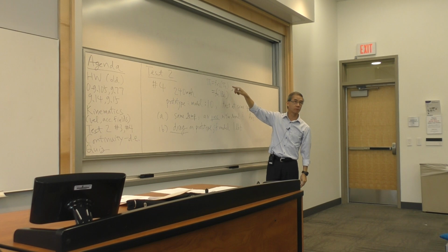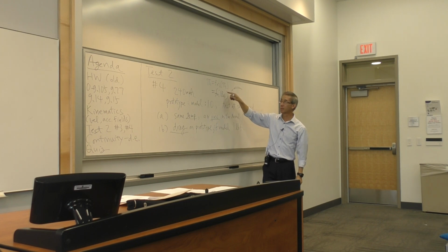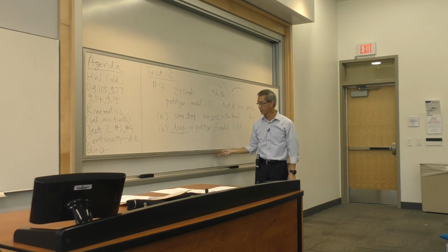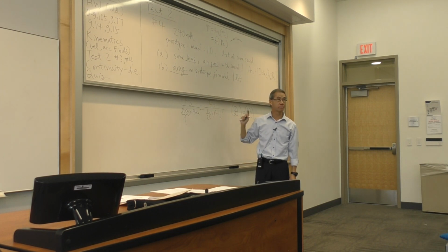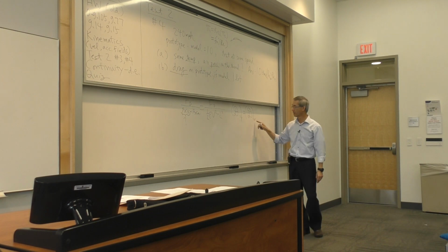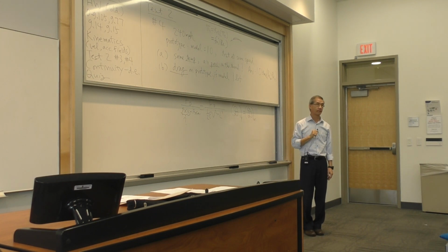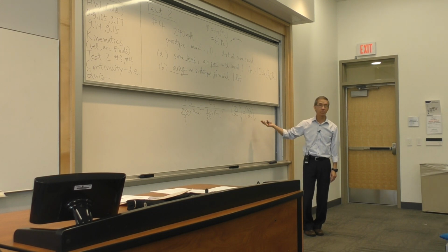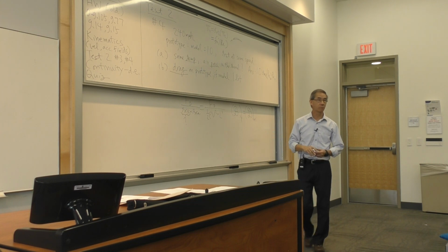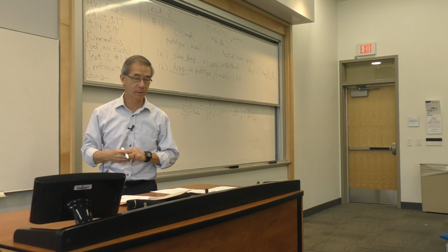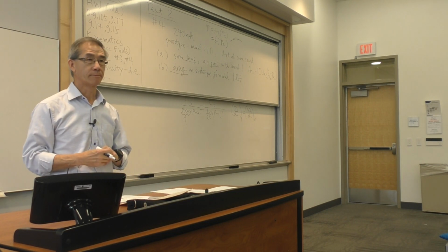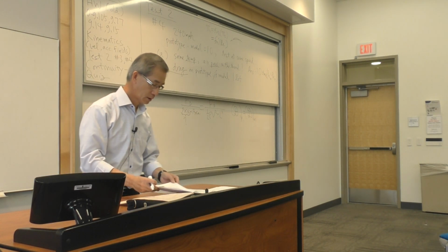There are only 2 pi terms. My Reynolds number, if they are matched, that means my pi 1 term, which is the drag coefficient, must also match between the prototype and the model. And that's it, and that's all you're asked to do. And by matching that and knowing the other parameters, you can get the prototype drag force. So it's a little detailed, but you can work it out once you have this background. Okay?